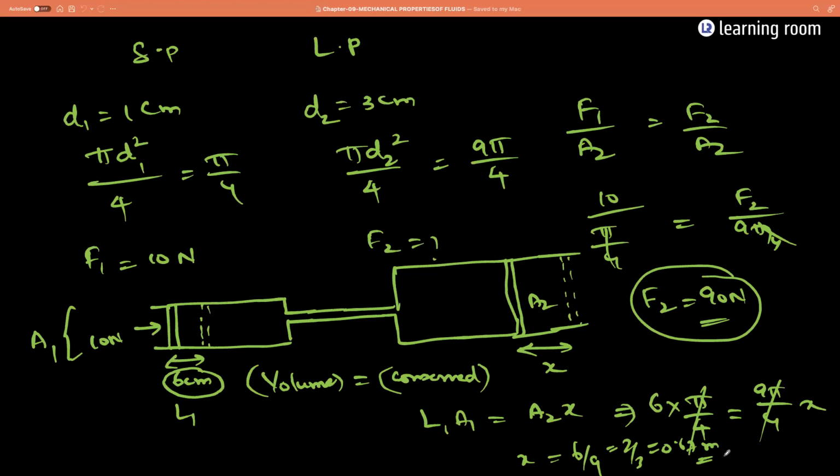Because liquid is incompressible, whatever is the volume that got covered should be equal to the volume that has got displaced here. So what is the formula for volume? Base area into thickness. So area of the piston is known, into the distance, which is the thickness. In centimeter is the move. So dotted lines are the new position.